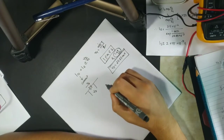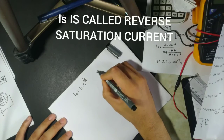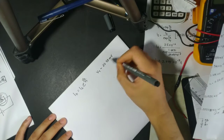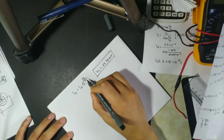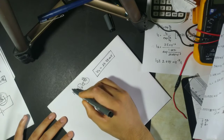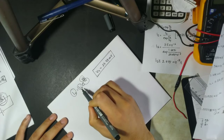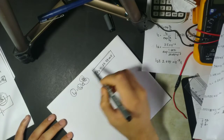Now the IS is called the reverse saturation current. We know that Vt is equal to 25.85 millivolt, so this is fairly constant. Now if this term in this equation is constant, and if this term is also constant, then we will have a clear relation between ID and Vd. That means we will not have to depend on any other quantity. We can just put the values and we get the answers.